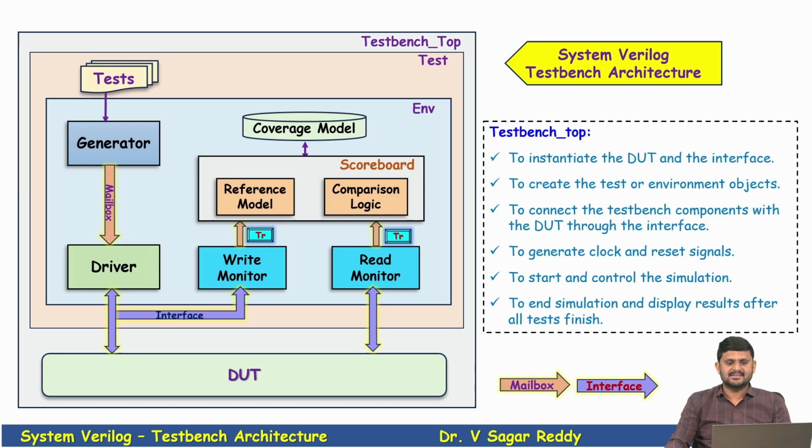So to conclude, the SystemVerilog testbench architecture is not just a collection of components. It is a precision-engineered verification system where the DUT is what you verify, the interface is how you connect, and the mailbox is how components communicate. The generator and driver create and apply stimulus.